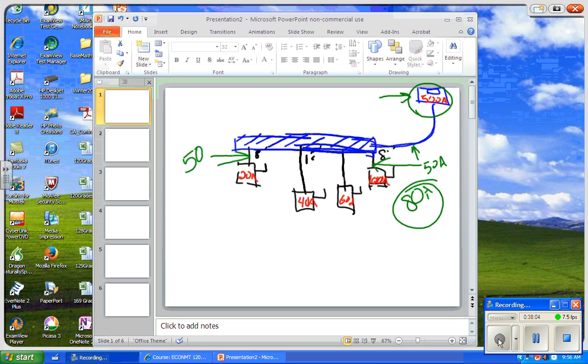But anyway, if our load is 80 amps on this circuit here and our tap rule minimum is only 50 amps, then we have to go with the 80 amps. We've got to do that. We've got to have tap conductors that will carry 80 amps if that's our load. Actually, we would have to carry 125% of our actual load. So if our load was 80 amps, then we'd have to have 100 amp wire there. Is 125% of 80 100? Or is it more? Might be. That's not really too important.